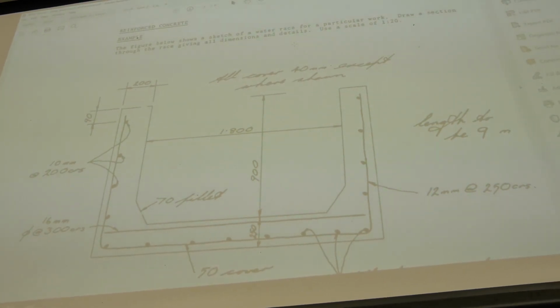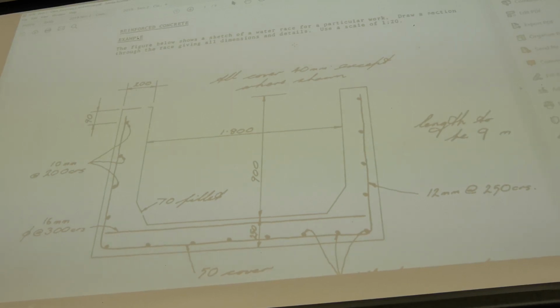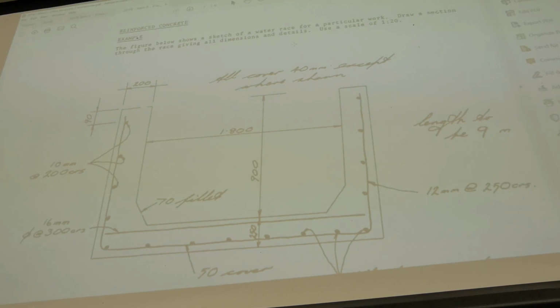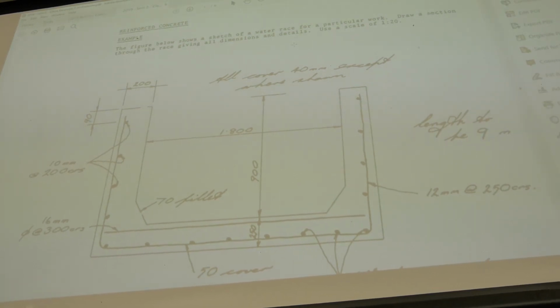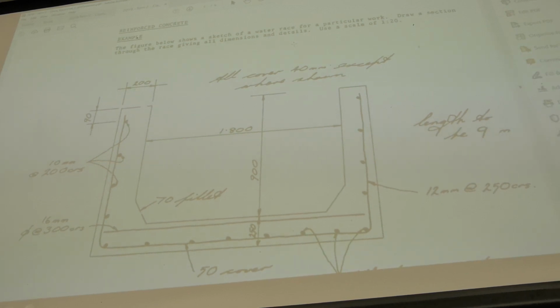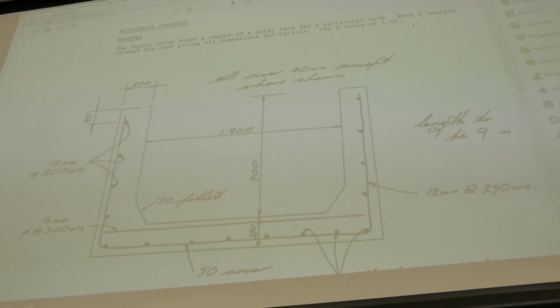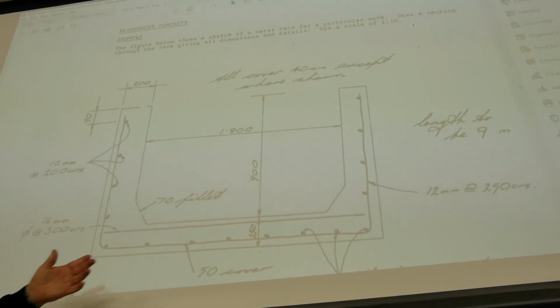This time you're wrong. It's 250 because the 300's a bigger gap, so you're making the structure weaker. So you always go for the stronger gap, the shorter gap, to make the structure stronger. Luckily, you don't have that situation in your assignment.